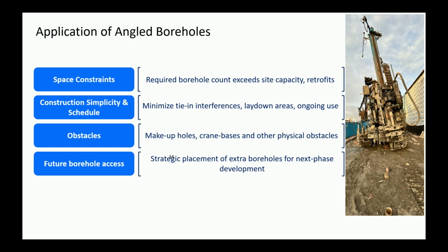And then the last one, I really want to talk about this. This is one that's often missed. So you've got a football field outside your university or school and you're like, okay, I'm going to put a field out there, I've got lots of room. And then 10 years later, the number of times that we've had these conversations going, oh, I wish we didn't have that bore field under that football field because we got a new building going in there. And so we're like, look, just put angled holes in and put them next to the existing building or the building you're building, and save all that stuff for future use and leave it alone. And that's sort of one of the drivers for angled holes for sure.